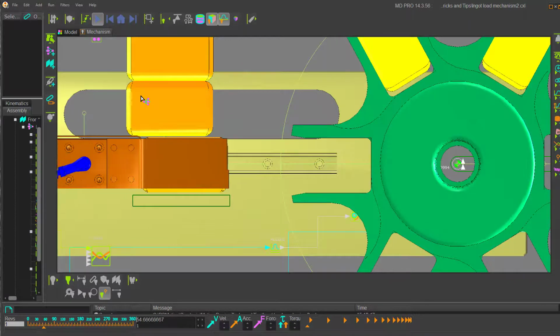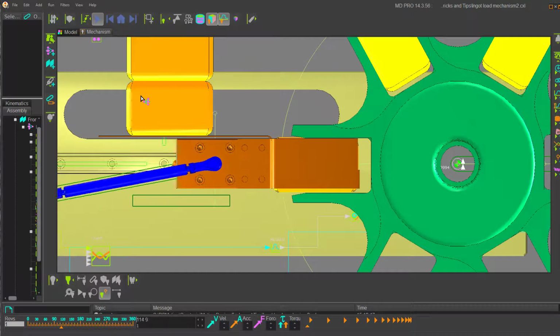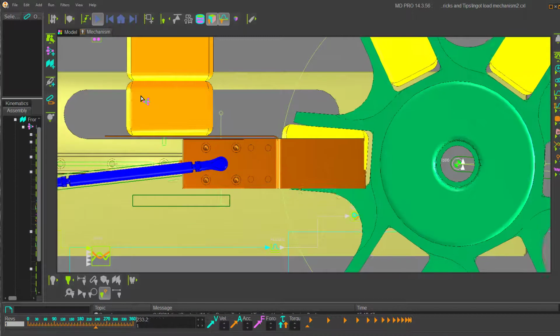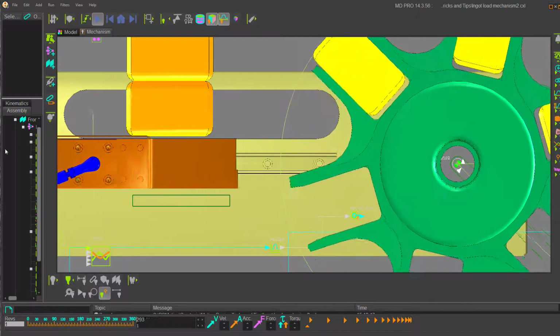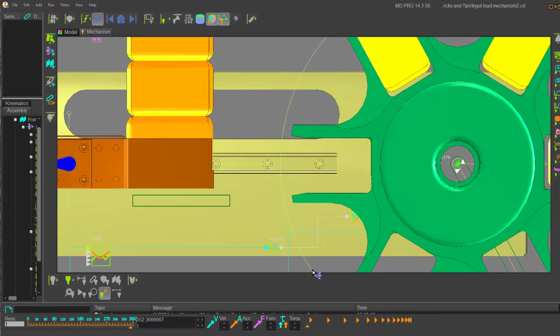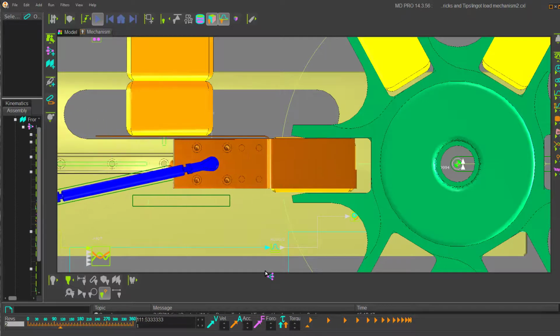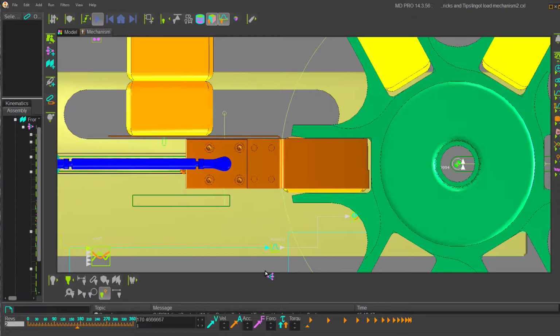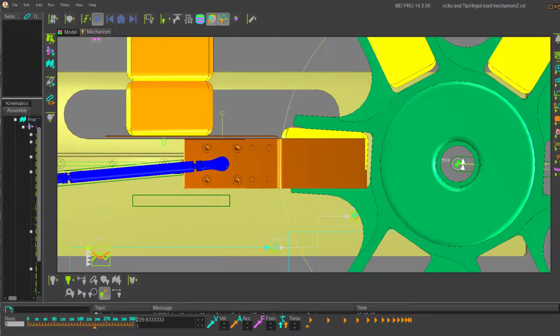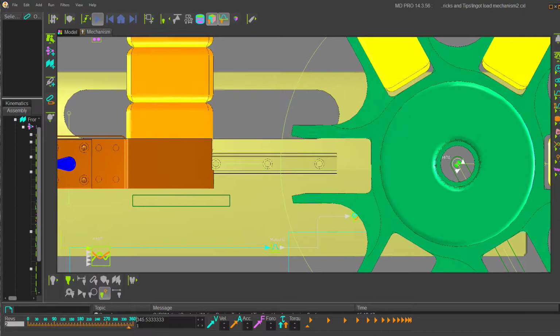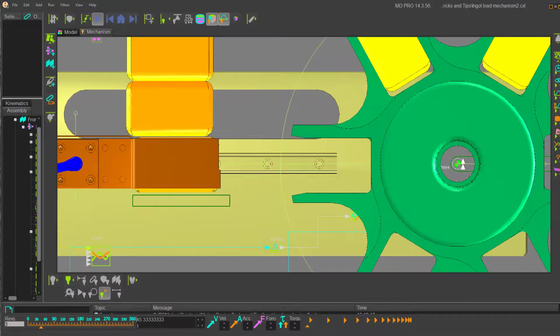Okay, and so the pusher is advancing. But this is really a tiny move. It's still not quite, it's still fouling on the ingot. So we've got two options now. We can either move the node of the pusher motion when it's at its most advanced position. We can delay that, but then that would undo all the good work we've done balancing the motion. But we have another option.